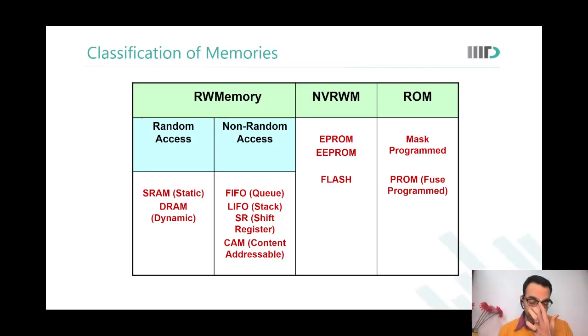chip, or enable a new set of features which are there in debug mode today, but once we validate them on silicon, we will want to enable them. So for the first few lots, the first few months, you give only the vanilla features. You program the EEPROM in such a way that only the vanilla features are available. And one year down the line, when you have well tested the additional features you had on the chip, you offer them also to the customer by just changing the program on your EEPROM.